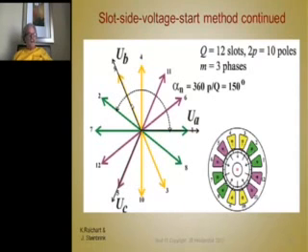All right, now how do we find the first coil location for phase B? You count 5 again. 1, 2, 3, 4, 5, 150 degrees. So here is where you number slot 3. Count 5 again, and that's how you number slot 4 that we're going to see over here. Count 1, 2, 3, 4, 5. Here's the first slot, which is slot 5. That's the first slot where phase C goes. And so on. You keep going around till you have all these slots numbered.